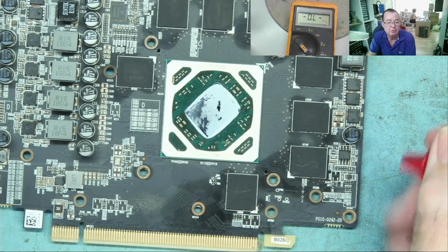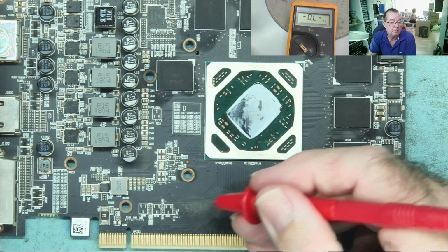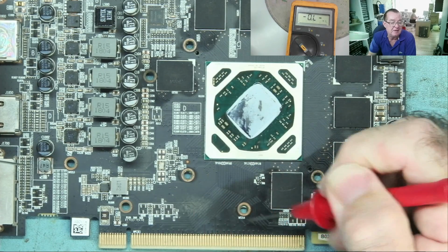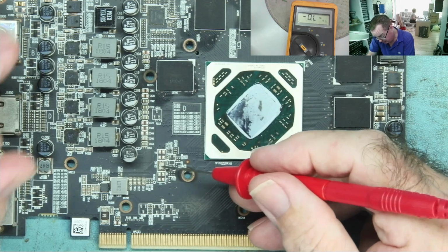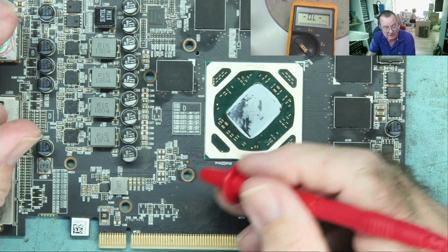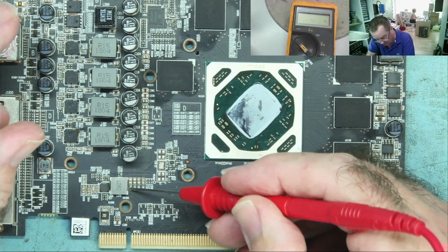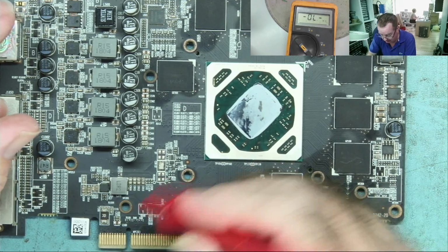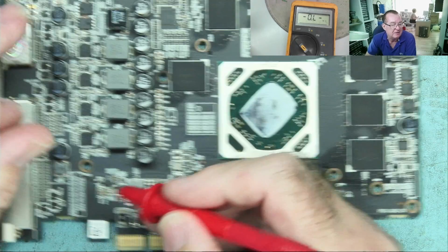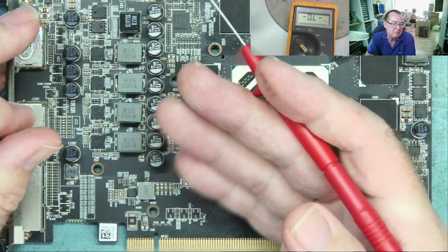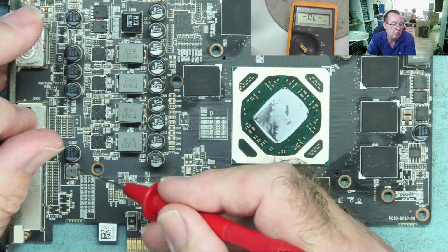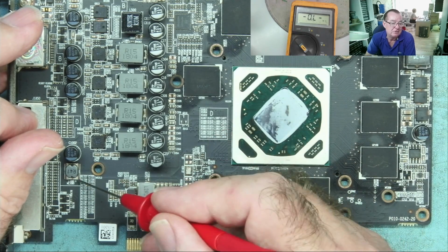How many more coils can we see? Well, there's one here. This is down near the PCIe, so this is probably PEX. And this will probably read somewhere about 20 ohms. Yeah, 15.7. Okay. There's another small one here. This might be the 1.8. Again, I don't actually know if it is, and because it's a small coil, I expect it to have quite high resistance.